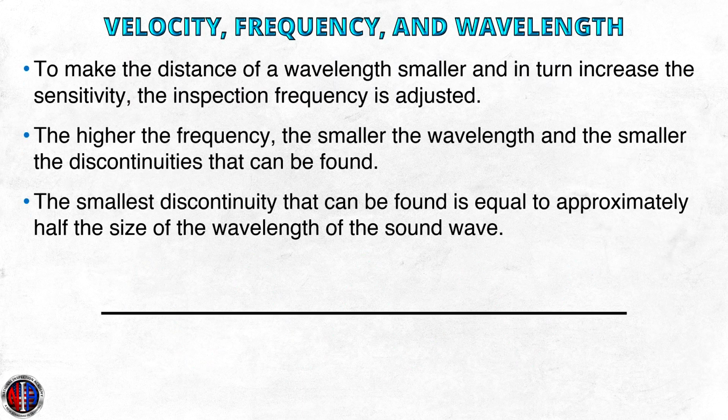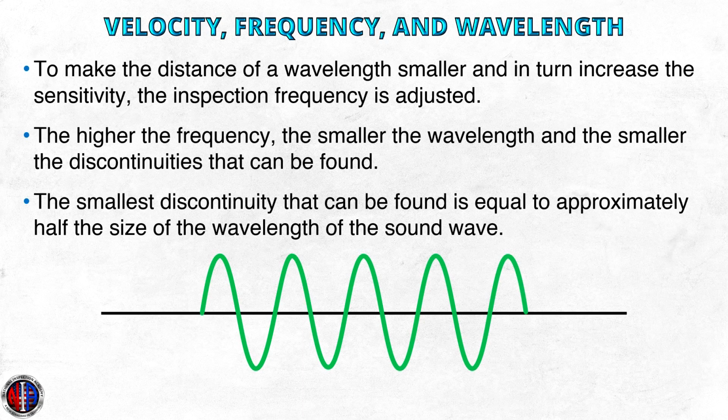To make the distance of a wavelength smaller and in turn increase the sensitivity, the inspection frequency is adjusted. The higher the frequency, the smaller the wavelength, and the smaller the discontinuities that can be found. By increasing the sensitivity, penetration ability is decreased.